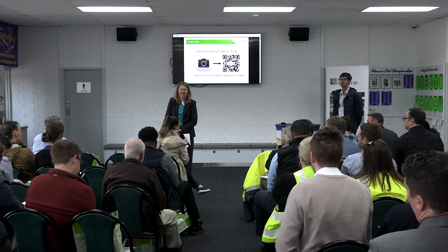Yeah, 50% volatilise almost immediately, and about 50% stay as a carbon source, because very little goes through. If you had a very fast draining system, say an impermeable system underlining your permeable paving, and it went straight into a pipe, then you might get hydrocarbons being flushed out of your system, but they won't reside in the actual permeable paving system.